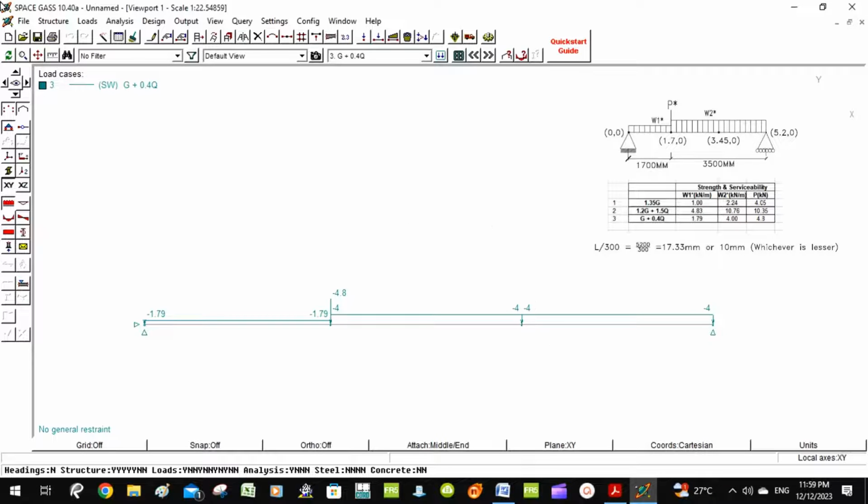Great. Now, first thing I usually go to is deflection. So load case 3 is a deflection for serviceability. Click on that and click on the deflection, and you can see here the deflected shape, and we have 9.67 and 9.7 around this node that we made.